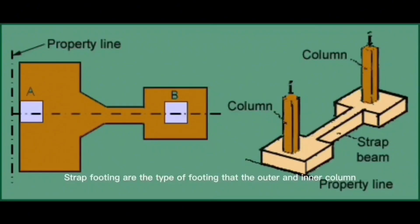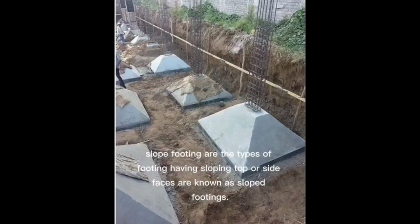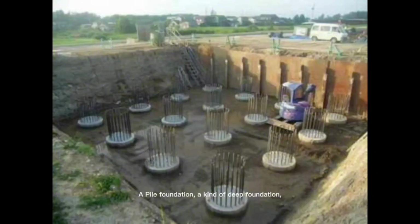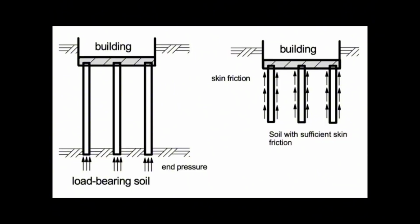Strap footing is the type of footing where the outer and inner column is connected by a strap beam, and the strap does not transfer any load to the soil. Slope footings are the types of footing having sloping top or side faces. They are useful in the construction of formwork. A pile foundation, a kind of deep foundation, can be defined as a slender column or long cylinder made of materials such as concrete or steel which are used to support and transfer loads by end bearing or skin friction.